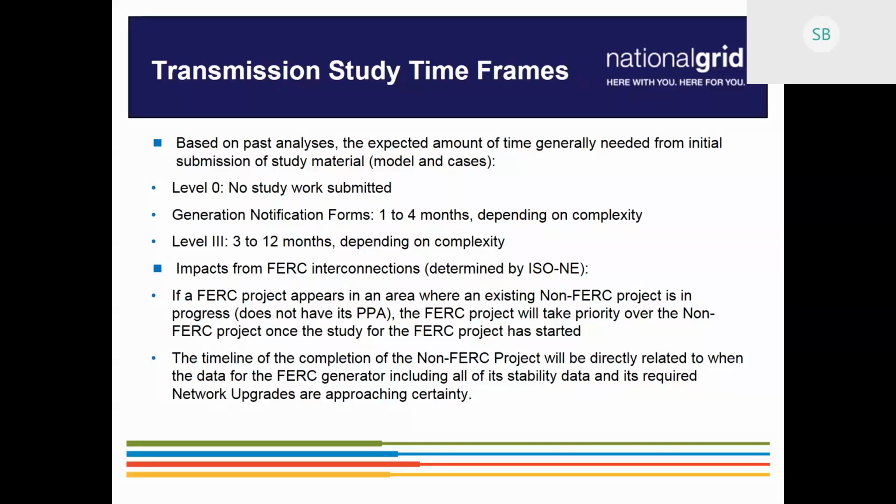It's three types of analysis. It's a load flow analysis, but also the stability analysis. We do faults on the different parts that are relevant to the projects, and we have to review what the performance is of the project and all the generation in the area. So the actual analysis takes longer there, and then we have to have that analysis reviewed by ISO New England. So it's both the analysis and review process by ISO New England.